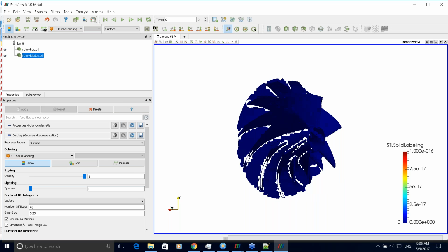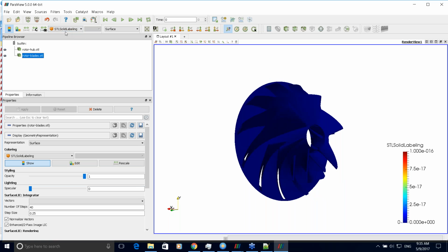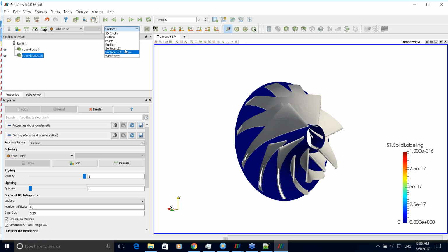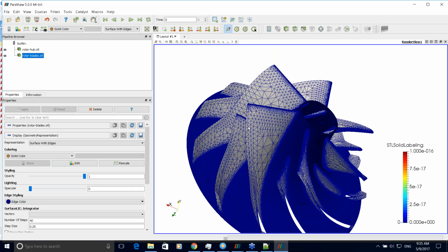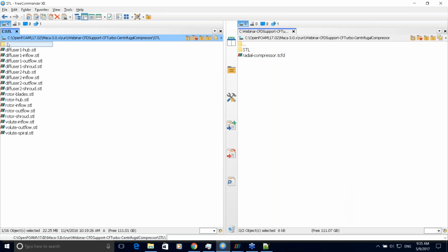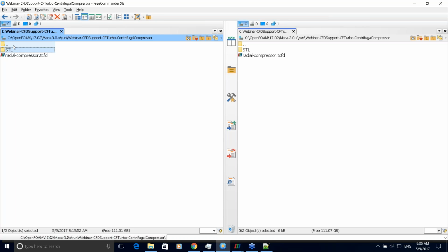This is the standard STL format with a triangulated surface. So this is the input. And yes, you can also start from scratch, to start constructing your own case with your own geometry, but with the connection with CFturbo, the job is simpler. And basically, for the first computation, there is no need to modify anything.